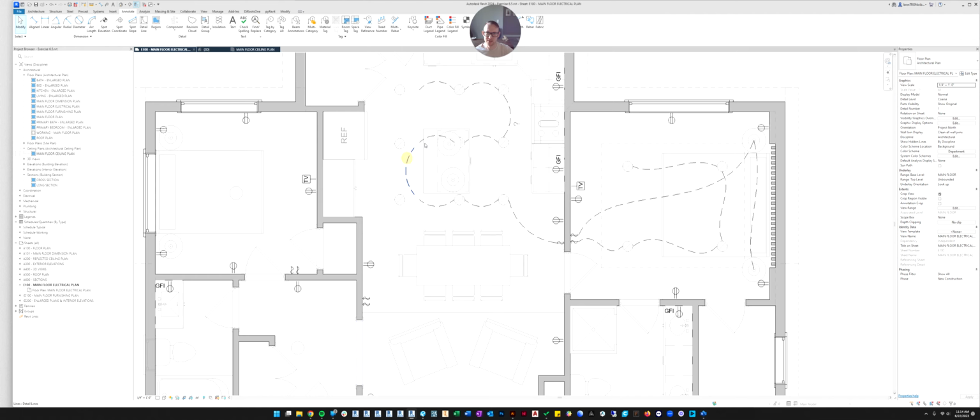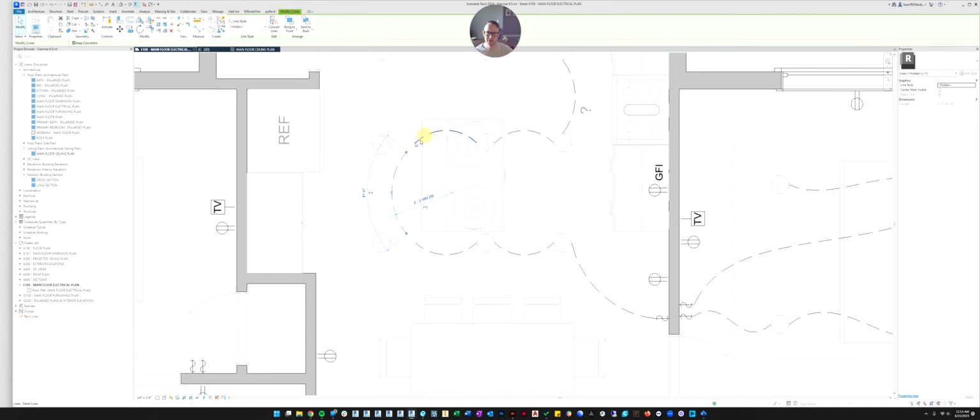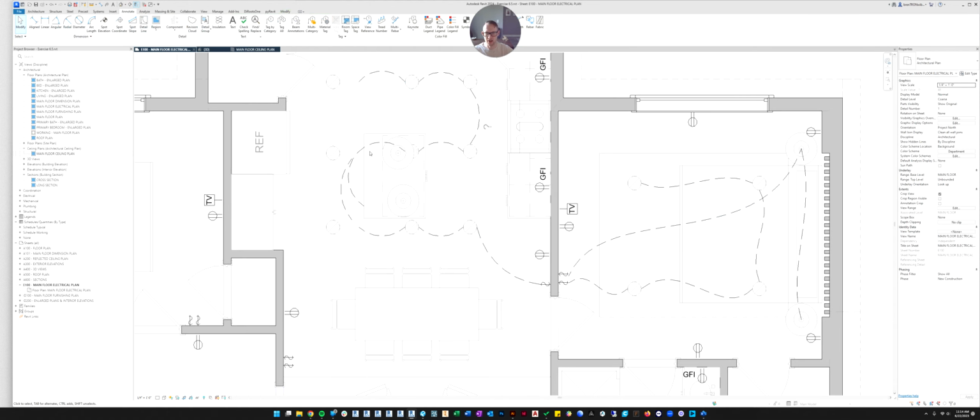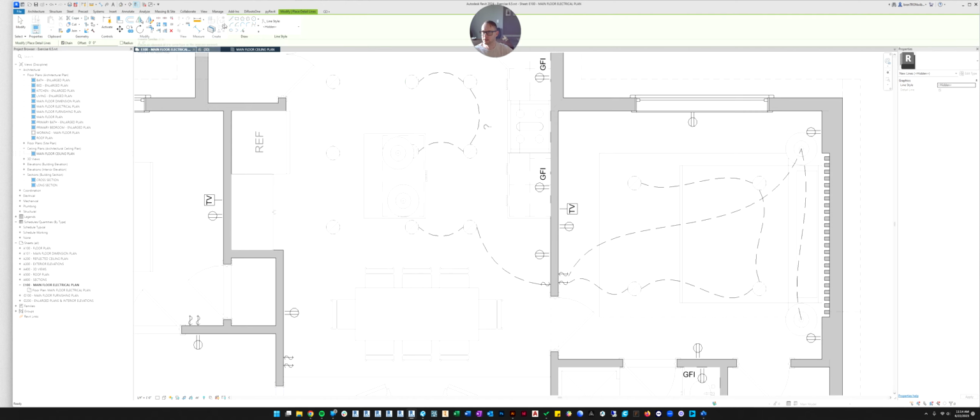But see right now, do you see how now our wiring diagram's off? You'd think you'd be able to just edit the line, but you can't. It wants to keep rotating. Or in the case of these, you could actually move these a little bit better, but it scales the whole line. So depending on how you're moving your lights, you may have to completely delete your lines. So I'm going to delete these arcs, and to get everything hooked back up, I have to completely redraw my arc lines. Right, I have to do this again, and I have to keep doing it all of these different times.